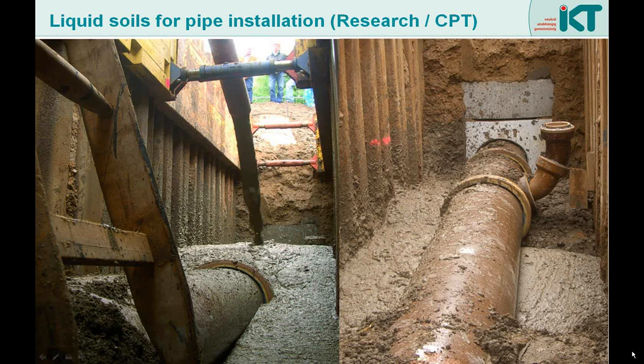On these pictures we can see the working principle. A liquid soil mixture is filled via a chute into the trench. The soil flows around the pipe and the whole pipeline has to be secured against uplift and buoyancy. After some hours, the soil congeals, hardens, and becomes a solid mass. The goal is to get a material that is solid but can still be dug up by using a shovel.